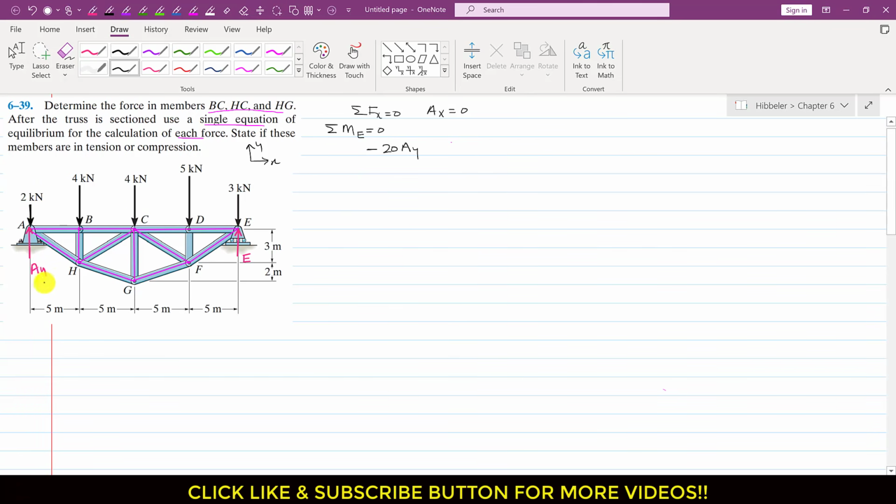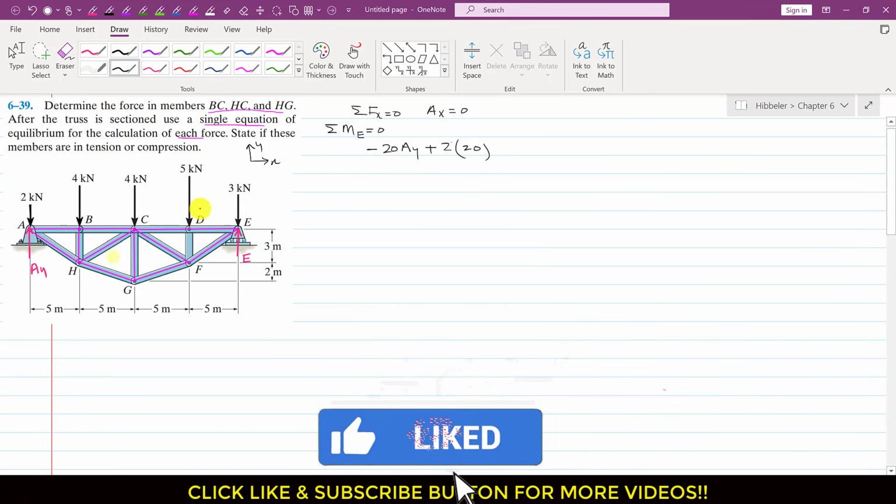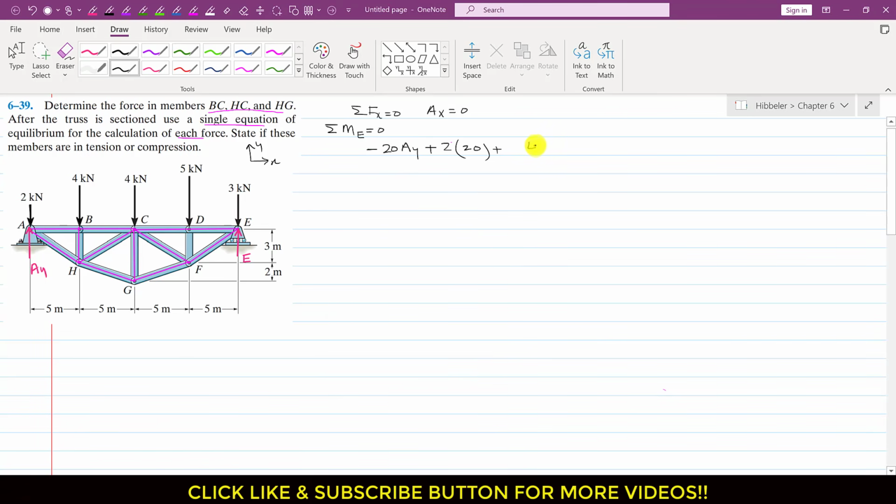Similarly, this 2 kilonewton force is producing a counterclockwise moment about point E. So I will write plus 2, and again the moment arm of this 2 kilonewton force from point E is the perpendicular distance, which is again these 20 meters. So I will multiply this with 20. Similarly, this 4 kilonewton force is again producing a counterclockwise moment, so I will write plus 4, and the perpendicular distance of this 4 kilonewton force from point E is 15 meters.